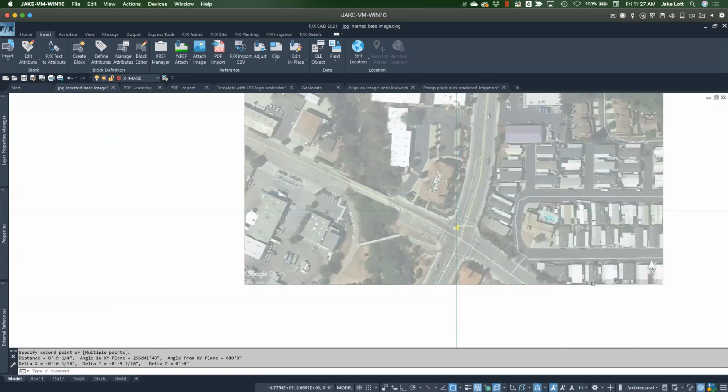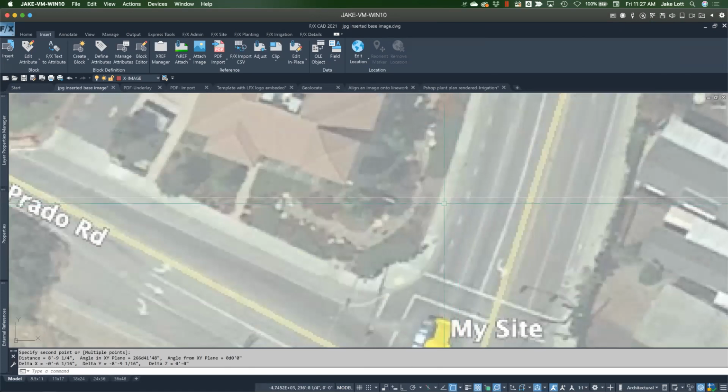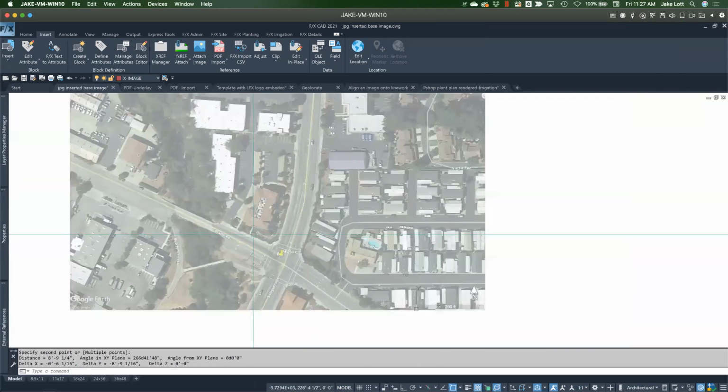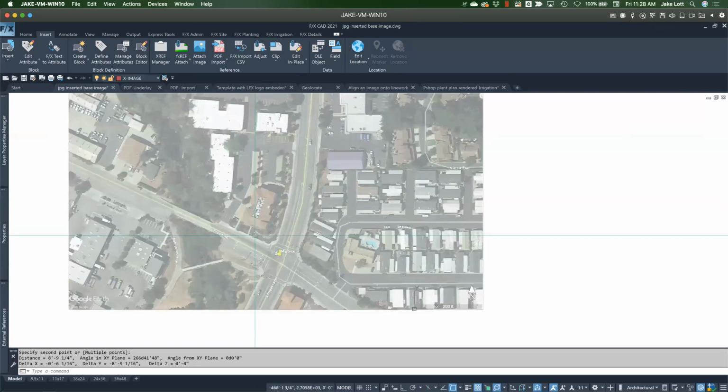So as you can imagine, something that's going to be a little bit up in the air, a gray area, is doing dimensions, making sure everything is exactly right, because we don't have anything to snap to, right? We don't have the proper real clarity on the lines and stuff like that. That's blurred. It might be within some of those pixels somewhere that we're measuring. It's hard to also measure the same place twice consistently. And that's, again, why we want to trace this line work and use that as the initial setup of those key elements so that we can go off of that instead of the image.